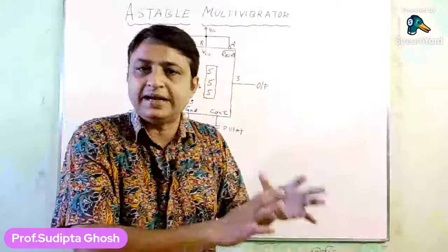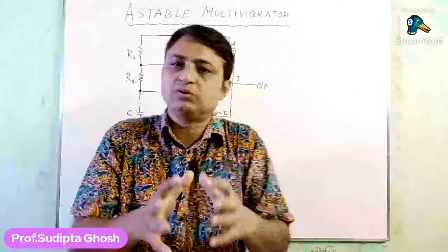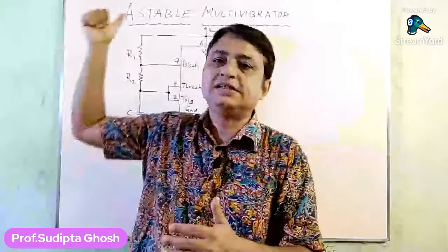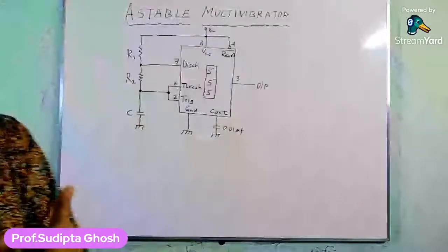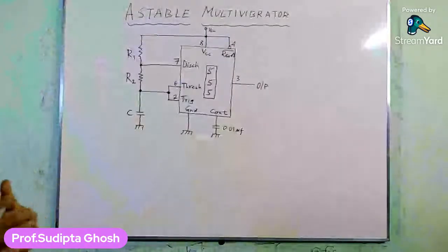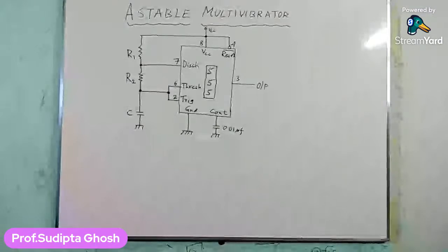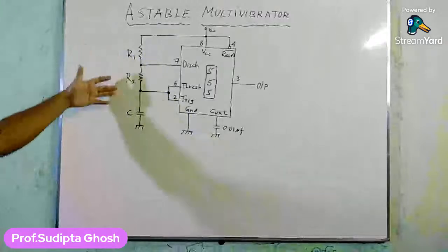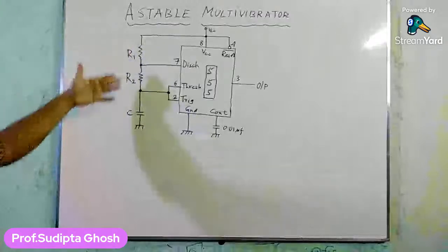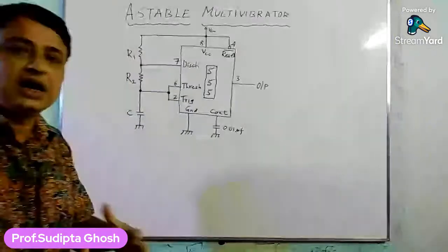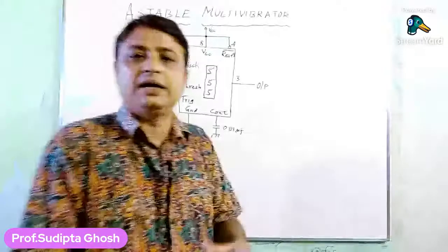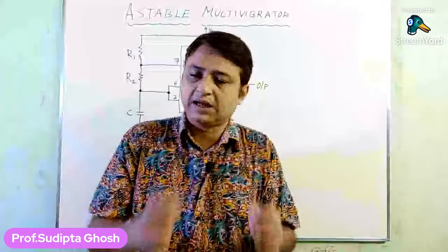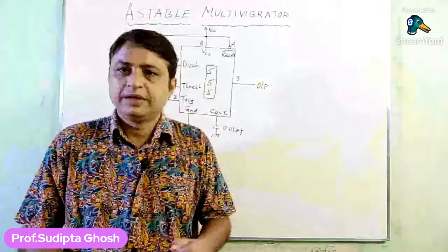So now the capacitor C can see the value of the voltage VCC here. So now the capacitor can be charged, and it will go on charging. The path in which the capacitor charges comprises these two resistors R1 and R2, which are in series. So the time constant of charging of this capacitor C will be R1 plus R2 into C. Okay, now the capacitor goes on charging.